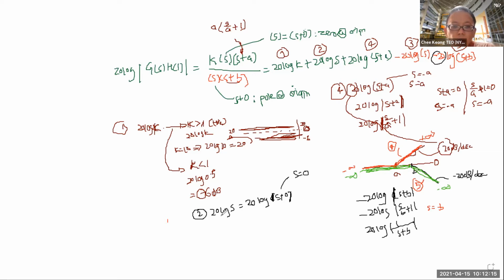If I have a zero on top, intuitively, if you think the same way as Form 4 and Form 5, then you should have a turning up at zero frequency. This is not wrong. This is correct. But the problem is, in the log scale, 0 is like negative infinity. It's very far away, so essentially you cannot see this zero. I'll explain why zero can never be put onto the scale. You won't see this point. It's very far to the extreme left.